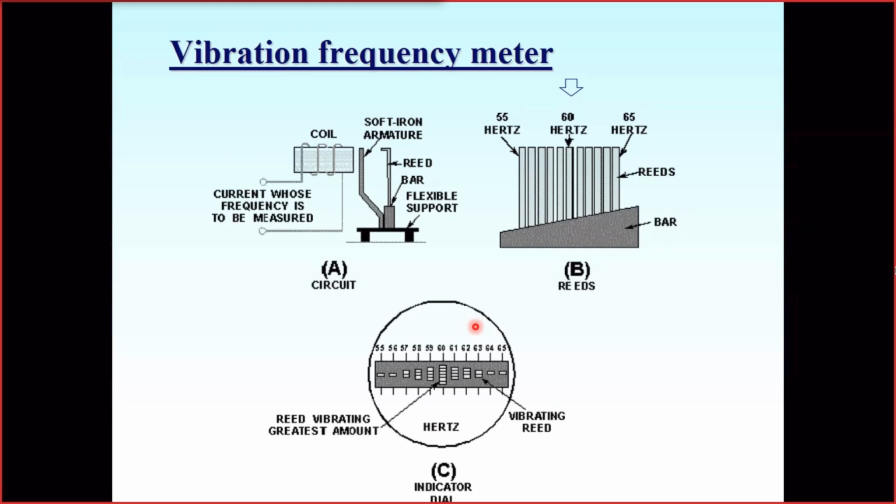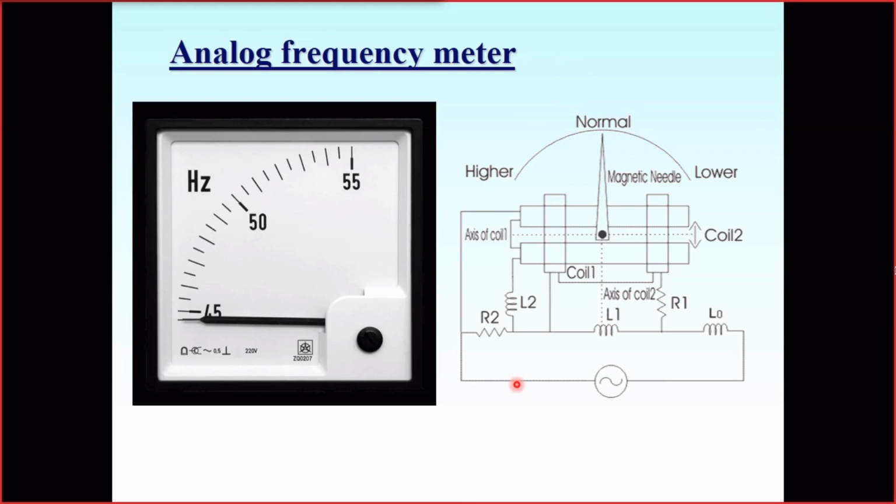For the United States, it has to be tuned to have its middle at 60 hertz, so that's why the range is from 55 to 65. For the European one, it will be from 45 to 55. So this is one quite interesting method to measure. Of course, I demonstrated it just out of curiosity, because to my mind the solution is quite elegant, some kind of mechanical vibration frequency meter.